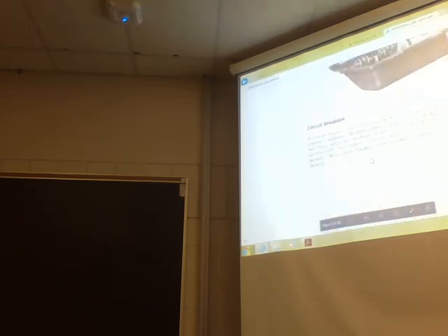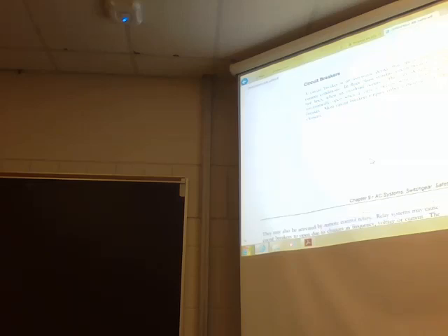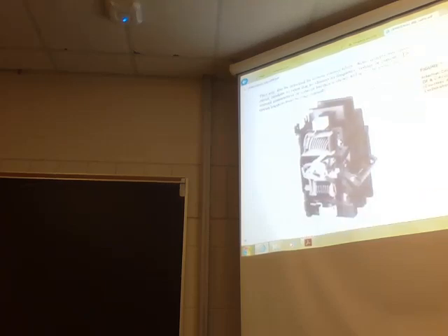Circuit breakers are an automatic device that open under abnormally high current conditions. In 3-phase systems, circuit breakers can open all 3 hot lines when an overload occurs. They are designed so that they will automatically open when a high current occurs, which exceeds the rating of the breaker. Most circuit breakers employ either a thermal or a magnetic tripping element. They may also be activated by remote control relays. Relay systems may cause circuit breakers to open due to changes in frequency, voltage, or current.